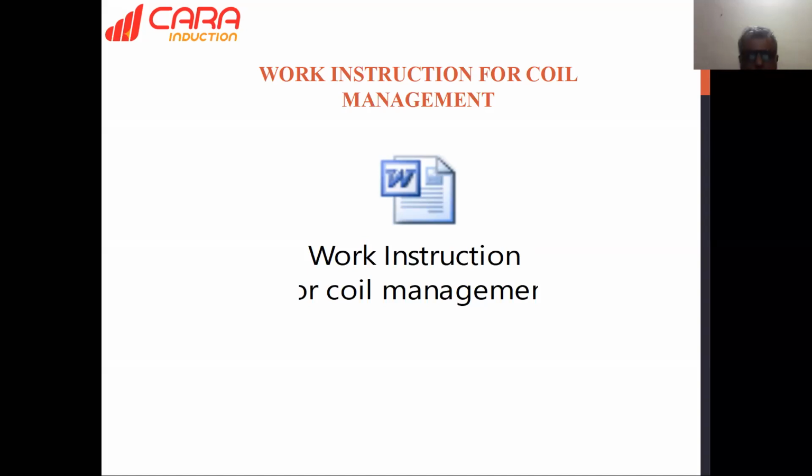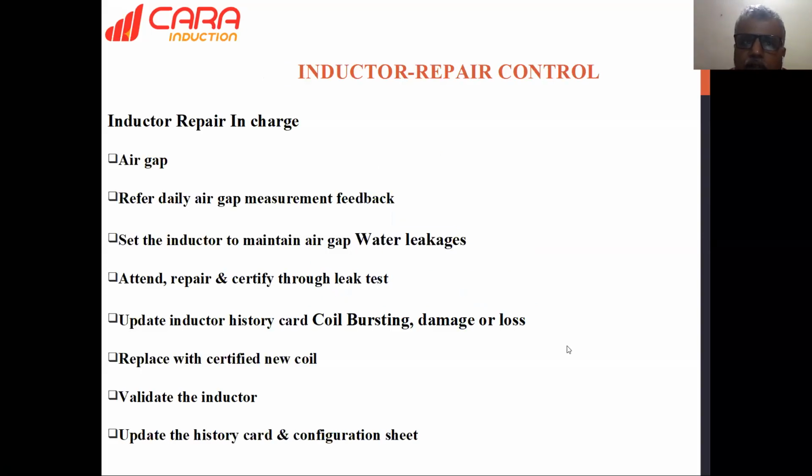One more thing, the make of the machine and the capacity of the machine we need to think about. As per the machine capacity and machine make, there is a requirement of inductor design in a round vertical machine. In some machines you are using single turn coil, double turn coil. It's according to our machine specification, machine capacity, and machine frequency.